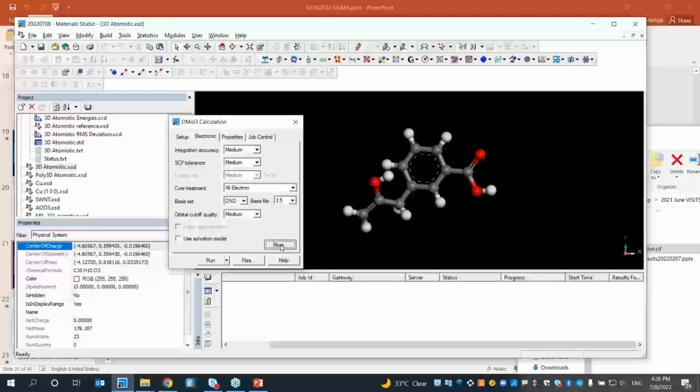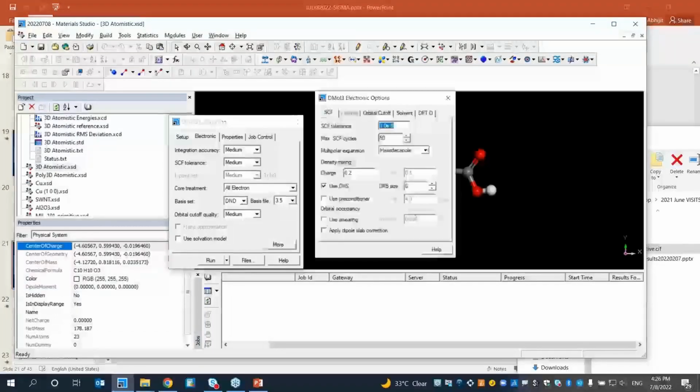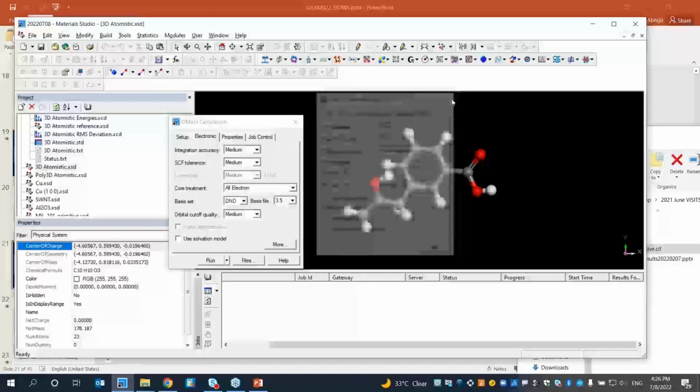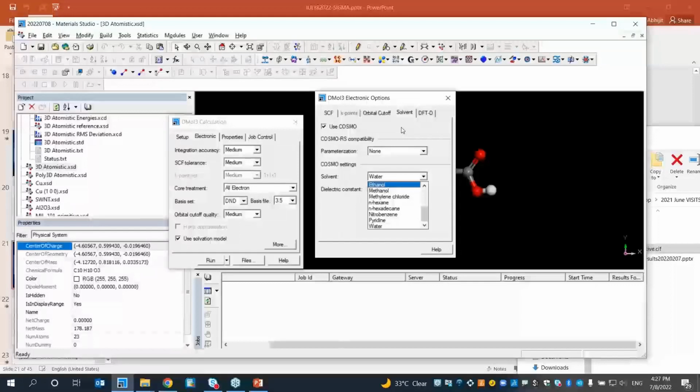So you can say, okay, I want to do 500 steps. I want to put in some solvent, like a dielectric constant. I can use a solvent with some dielectric constant, like water or ethanol or a mixture. I can use that, and then we can calculate properties. And this DMOL is used for chemical properties, like the Fukui function, orbitals, reaction energies, kinetics, and all these. And we have another tool which is for periodic boundary conditions.